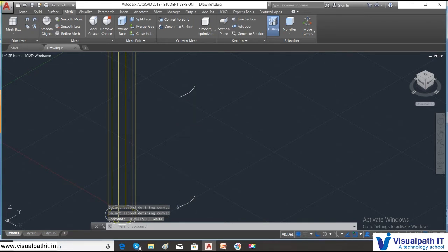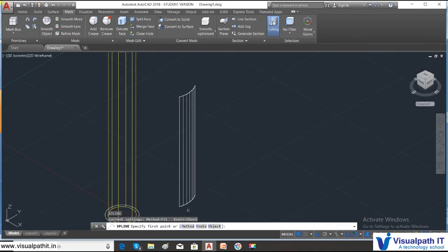But when I select it here and when you give the command rulesurf, and when I select it here and here, that will create a cross surface. So give the command rulesurf, select and select, and then use a copy or an array.